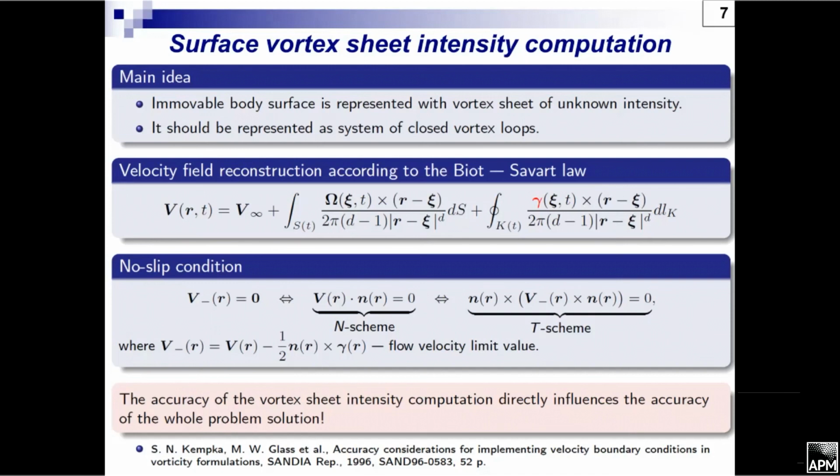The idea is nearly the following. For example, both the report from Sandia Laboratory that I mentioned and some results obtained by Professor Dimitrova write down the integral equation with respect to vorticity flux, which is the speed of vorticity generation on the surface. If we try to solve this equation exactly with respect to vorticity flux, the accumulation of error will be dramatic. But in the framework of our approach, we take some simplifications and assumptions.